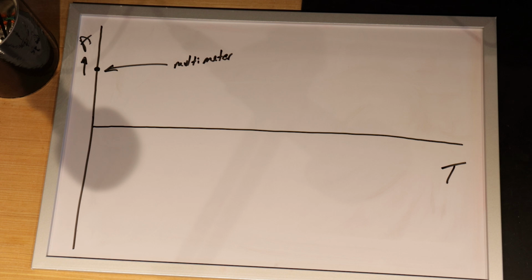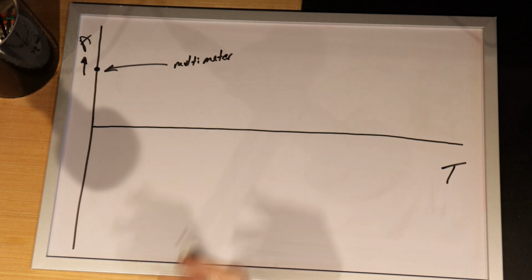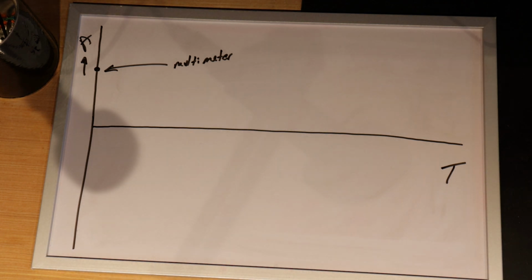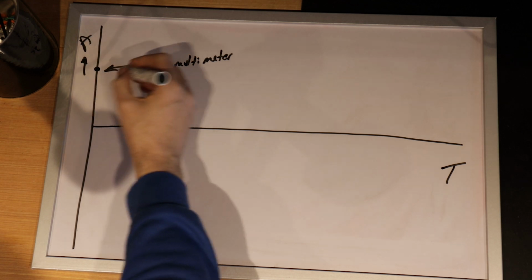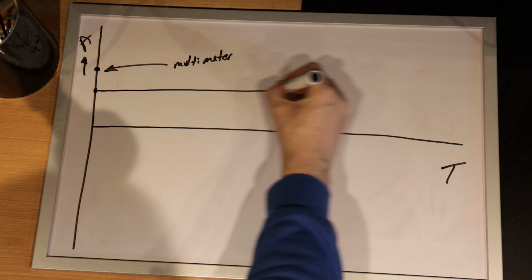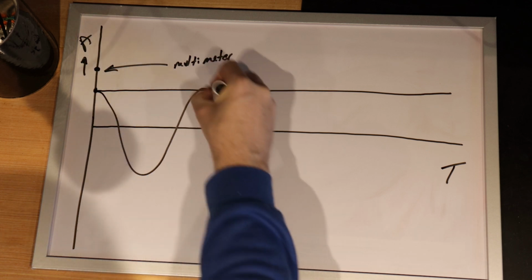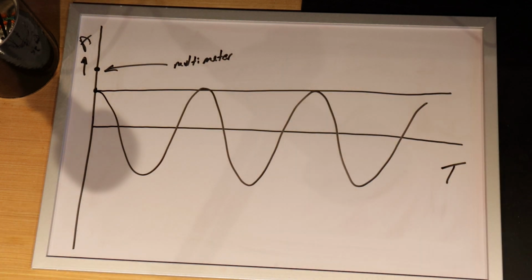If you have an AC and DC switch on the multimeter, you can see by changing it from AC to DC if you have a repeating value, if it's static. Looking on a multimeter, a DC signal would be like that, whereas an AC would be like that or similar.